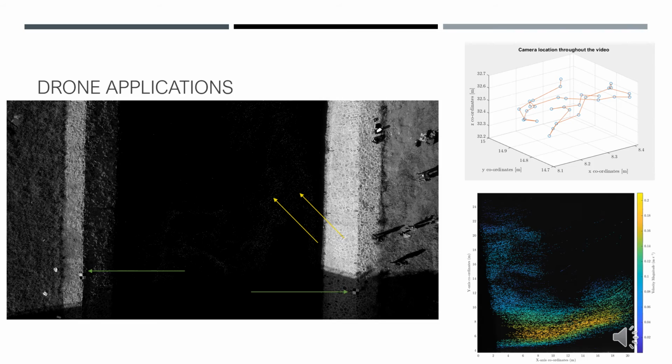And you can clearly see the change in velocity from the edge of the bank, but also how there's a lack of traces in some sections of the video. For good, reliable data, we would hope to see results as uniform across the river as possible. So it's safe to say for this video, either more video was needed so that the traces had time to flow all the way to the top of the image, or more traces were needed and dispersed more evenly.